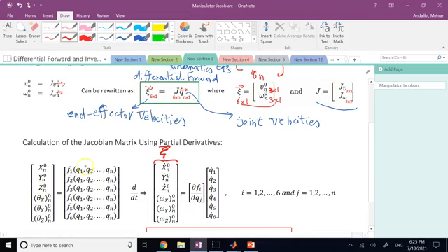So this whole thing here is that zeta is equal to. So here these functions f1, f2 all the way to f6 are functions of q's, but I'm taking time derivative from them. Since they are not function of time explicitly, they are function of q's. The q's are functions of time. So again, here I have to do the chain rule.